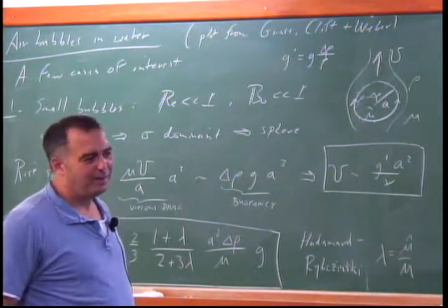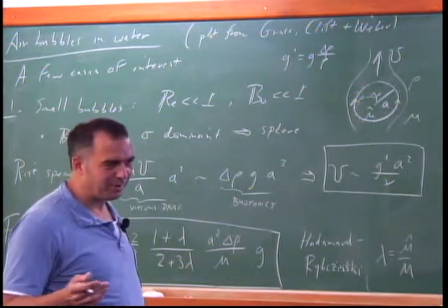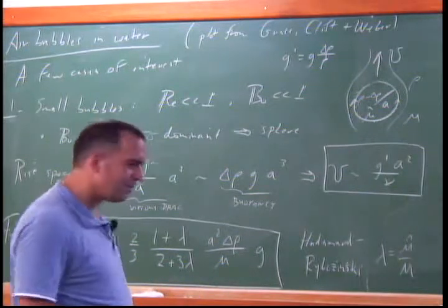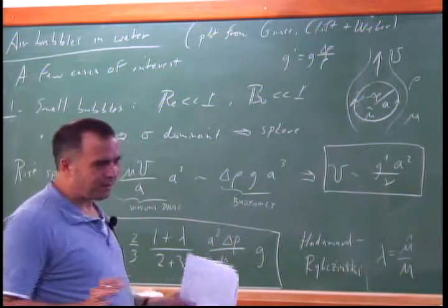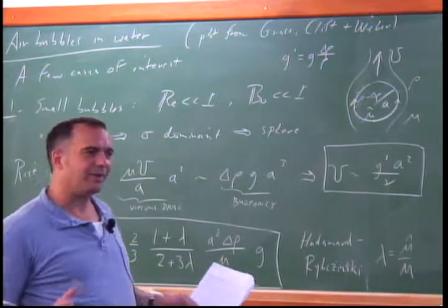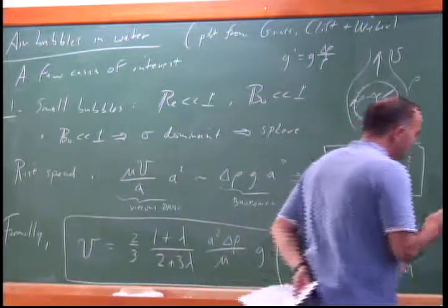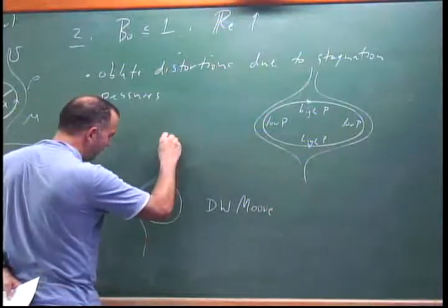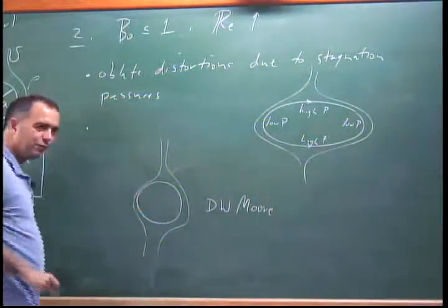And you get into all sorts of trouble when you do that, because you find that the drag on objects moving in potential flow is 0. The reason is you have a no-slip condition which you can't take into account. So if you have a rigid object moving, you get it wrong because the potential flow solution doesn't have a stagnation point. You can basically solve for it, and it's moving by as if there's no drag whatsoever.